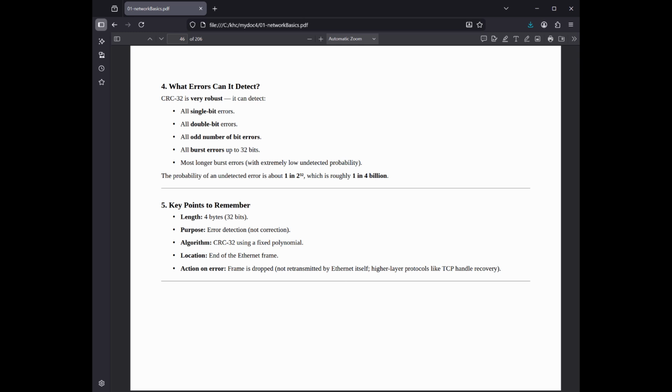Reflected form, 0xEDB88320. Due to historical reasons related to how the first Ethernet hardware transmitted data, least significant bit first within each byte, the standard algorithm involves a process called reflection or bit reversal during the calculation. Many software implementations use a reversed polynomial constant, 0xEDB88320, along with specific initial values and final XOR steps to achieve the same result as the hardware-oriented IEEE 802.3 specification. Modulo 2 arithmetic: the division process in CRC is performed using modulo 2 arithmetic, binary arithmetic with no carries, which simplifies complex addition and subtraction operations to simple bitwise XOR operations.